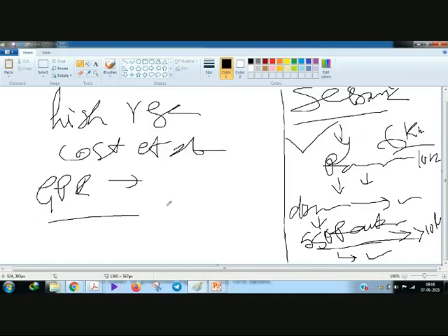But it will give you a high resolution shallow subsurface survey, and seismic generally does not work in hard rock terrain. So that's why GPR is required for investigating the water table. See, water has low economic value.